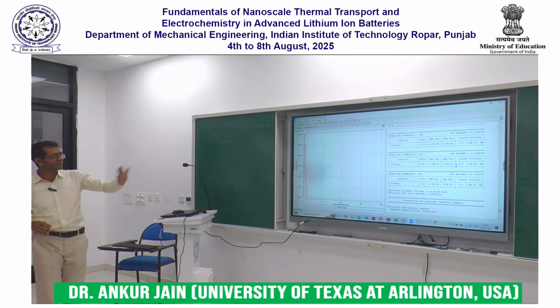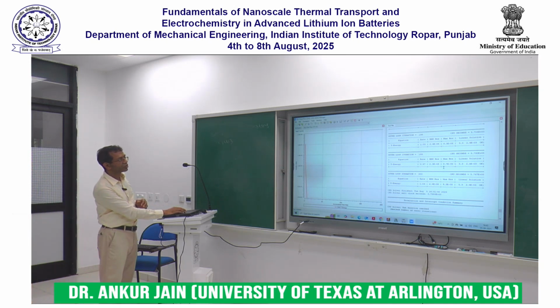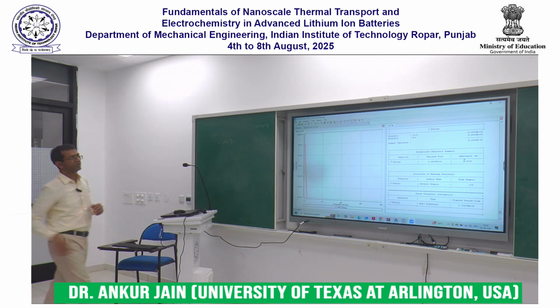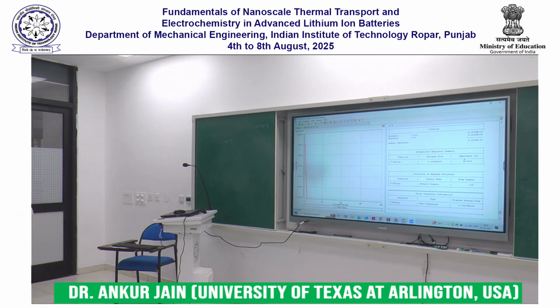And then there are some other things here. For example, you should always look at the residual criteria, the imbalance criteria. You see, it is telling you that the total imbalance in the problem is pretty much zero, which tells you that you have solved this problem very accurately. This happened so quickly because this problem was extremely simple. It was perhaps the simplest problem one could think of. Any problem that is more complicated than that will take some more time and effort to solve.